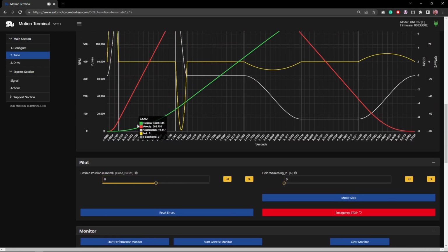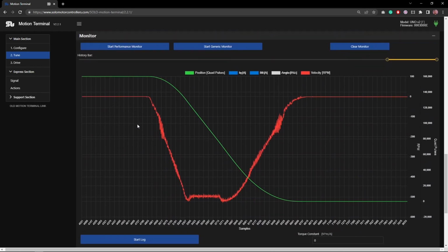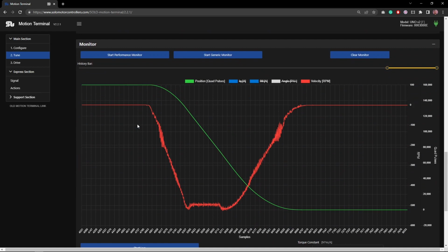You can have it also differently for different scenarios, but this is very flexible because you can tune the motion profile in a way that, for example, once you're landing, you have less back EMF or less, let's say, regeneration through having slower acceleration or deceleration. And this is very handy for position controlling applications.